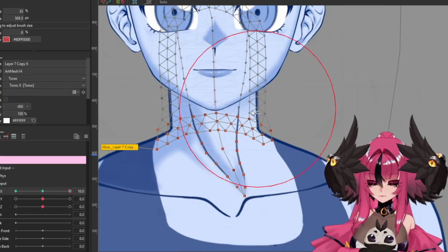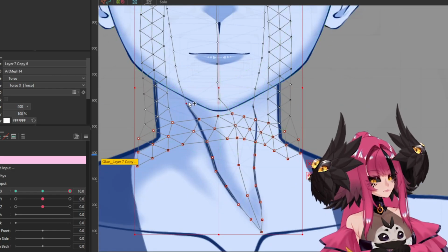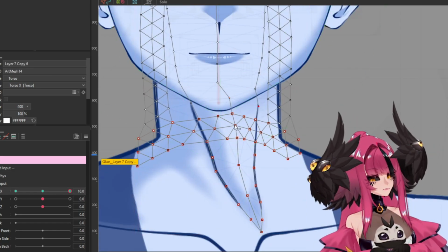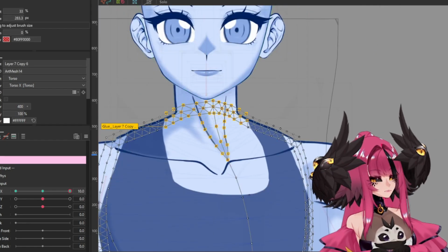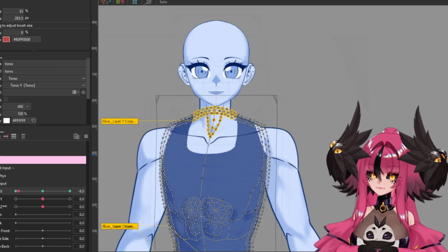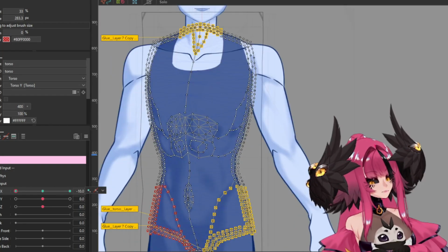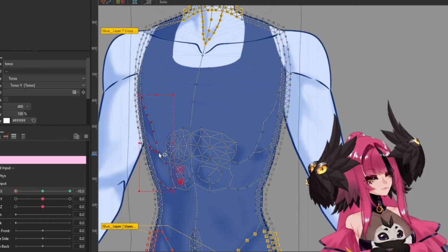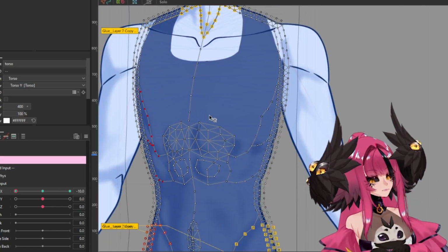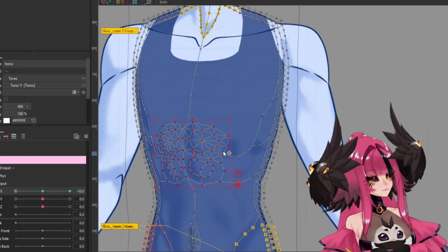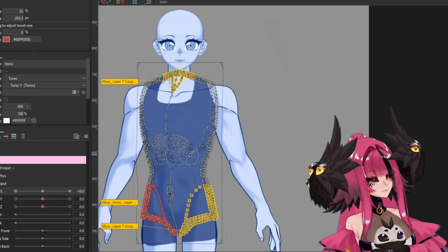into the position that you want on both sides, we're going to do the depth to those abs and muscle components that we were talking about earlier. So at 0, we're going to make sure that we select the inner circle or the inner parts of each ab. And you can do this by holding shift and using the lasso tool and selecting each part entirely. And then we are going to go back over to the left or the right, and we're going to grab the center of all of those verts, and we're going to slide them closer to the side that we are turning, and you will magically have a bit more depth.